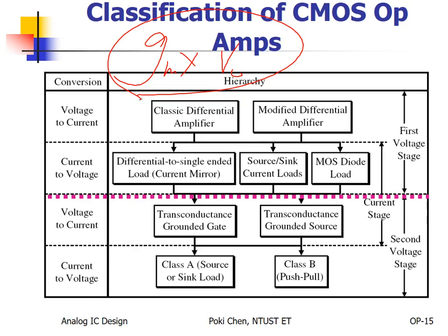How to increase your gain? If the gain is not good enough, there are two major ways. Either you increase the transconductance or you increase the output resistance. But nothing is free. If you would like to increase GM, usually it means very large transistors need to be used. So to save money, usually we hope we can increase RO. If you can, usually we increase RO.